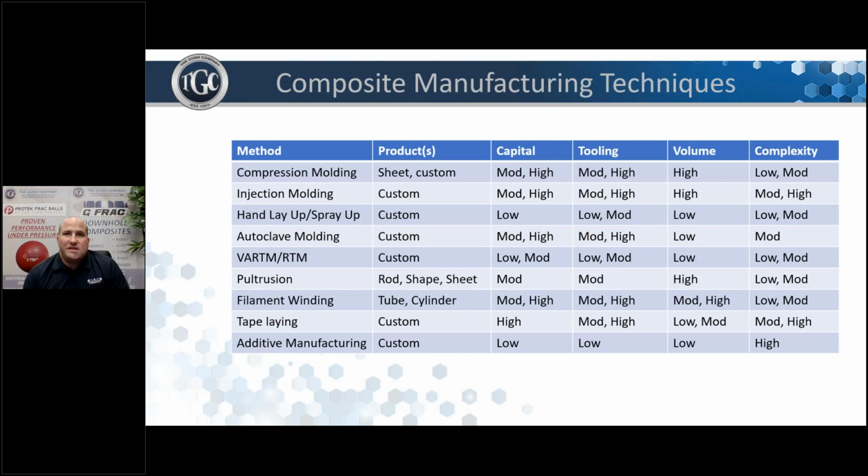This table is intended as a summary of costs of what we reviewed and a few we did not go over. Sometimes some initial questions about volume and complexity can help rule out certain manufacturing techniques. High volume parts tend to require a higher capital investment for the tooling that's required. Now, with the introduction of additive manufacturing, prototype composites can be made for fit and function prior to making the investment into injection molding dies. It has been a huge benefit for many designers.